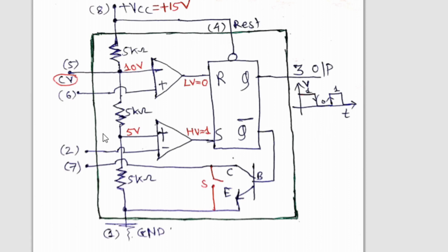Now this is the internal block diagram of IC555, which is used to generate the square wave at the output by connecting externally connected capacitor C along with RA and RB in the circuit diagram. After this we are going to observe the circuit diagram, and then we are going to study how all these 4 blocks work.